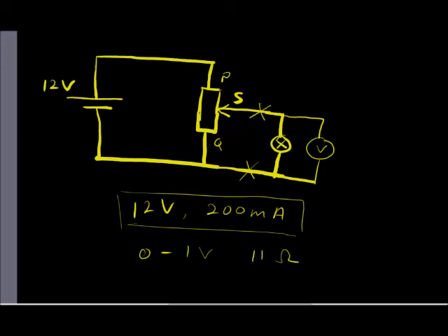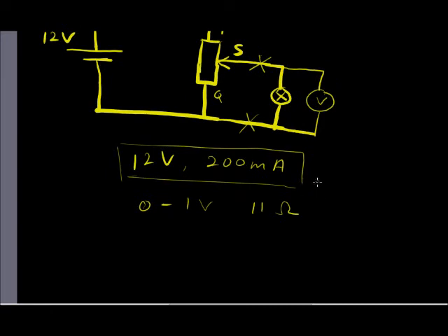So it seems like the resistance of the lamp is not constant all the time, and it's understandable because, as we learn from physics, when the temperature of a conductor, especially a metal conductor, is higher, the resistance is also going to be higher. So when the lamp is operating at the normal operating point, there will be more current flowing through.